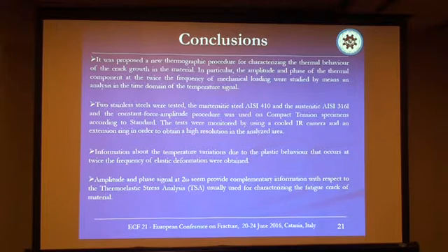Information about the temperature variation due to the plastic behavior that occurs at twice the frequency of elastic deformation was obtained in this work, and the amplitude and the phase signal at twice the loading frequency seem to provide complementary information with respect to the thermoelastic stress analysis usually used for the characterization of fatigue cracks in materials.